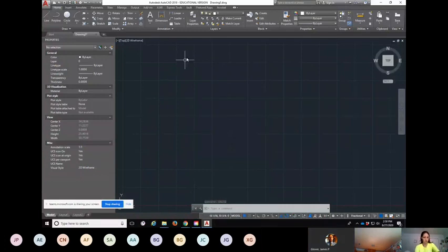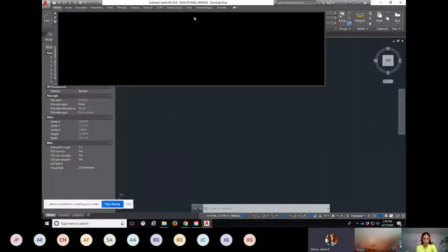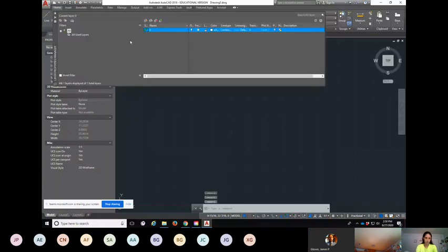Now, one of the things about AutoCAD is you have the same availability of this in AutoCAD Web App. But as I said, I haven't played around with AutoCAD Web App that much. Here, I do know that you're going to have to be able to manipulate layers in the Autodesk Certified User Exam. And so what we need to be working with is creating layers and working with layers. If I want to create a layer here, everything starts with layer 0. That's your base layer.